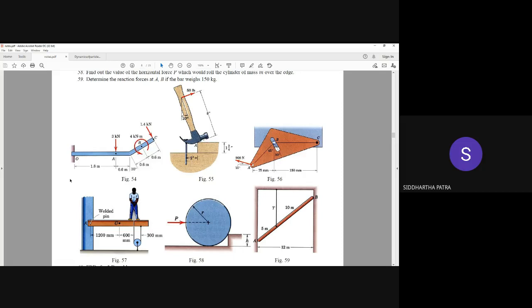System of equations I'm talking about. So maybe in your calculation you have included the moment that is there as a reaction. So the complete diagram should be with two force reactions and one moment reaction. Maybe you have done that in your calculation, but many of you have not shown it in your free body diagram, and that means it's an incorrect solution to the problem. Okay.